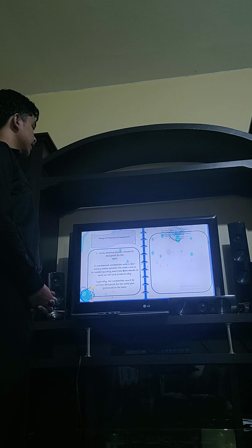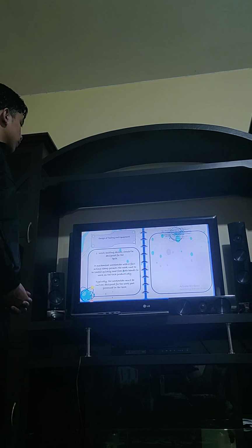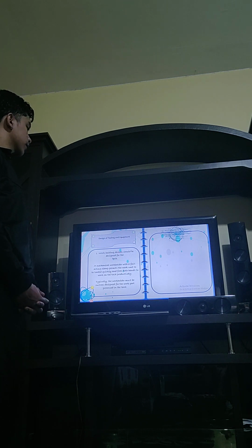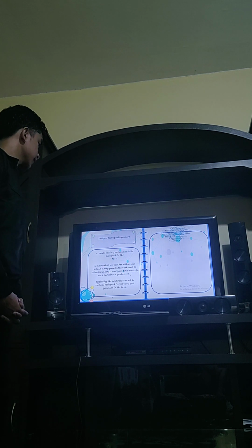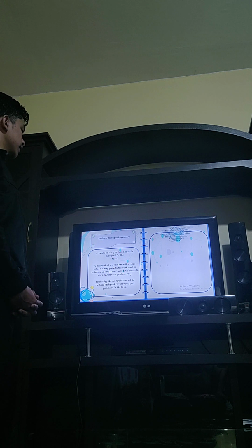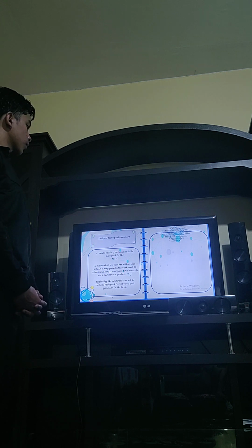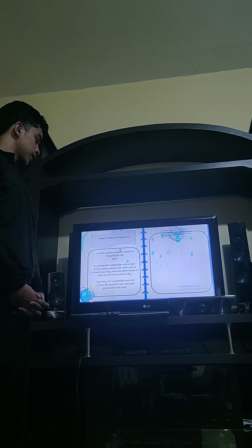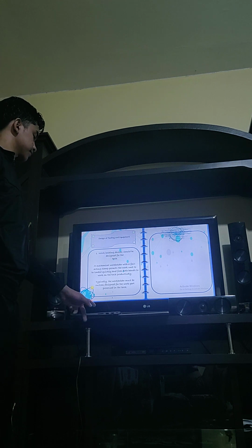Design of tooling and equipment. Number 1, work holding devices should be designed for the task. A mechanical work holder with a fast-acting clamp permits the work units to be loaded quickly and frees both hands to work on the task productively. Typically, the work holder must be custom designed for the work part and process in the task.